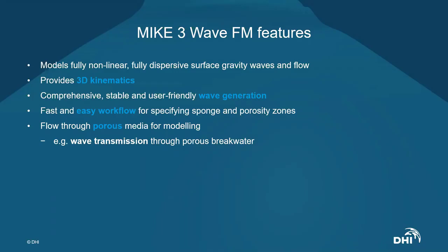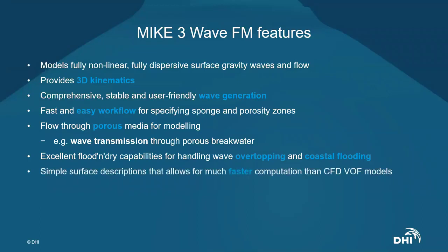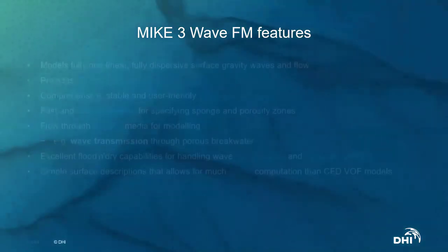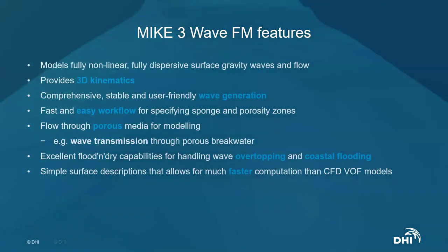I should say that the porous flow is approximated via the Darcy-Forchheimer equation, where we have different calibration coefficients for the turbulent and laminar resistances experienced by the flow as it goes throughout the porous area.